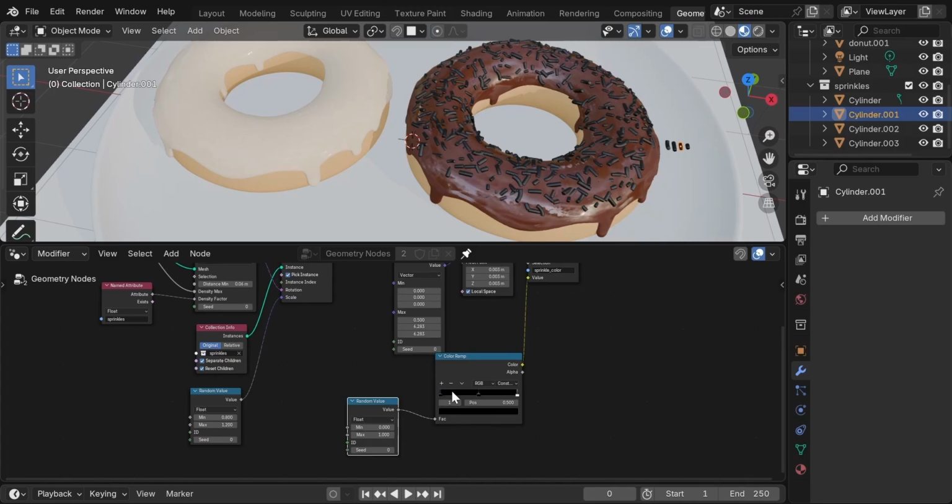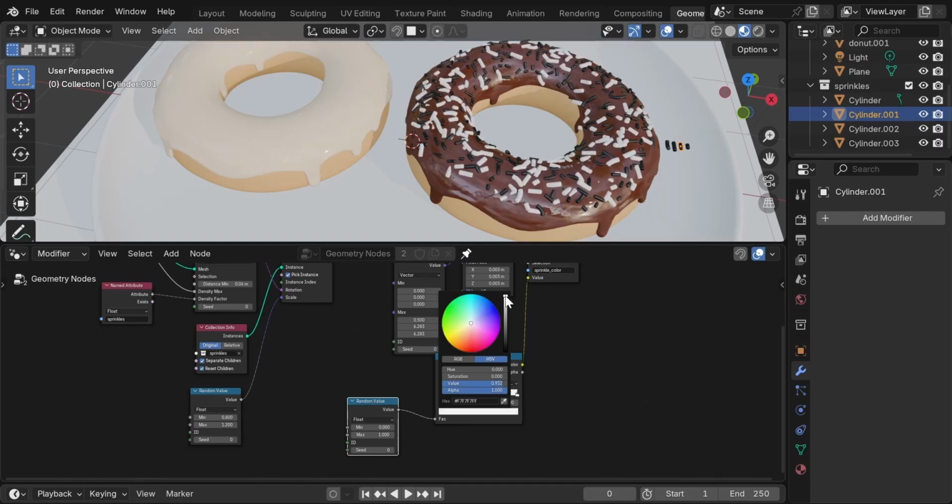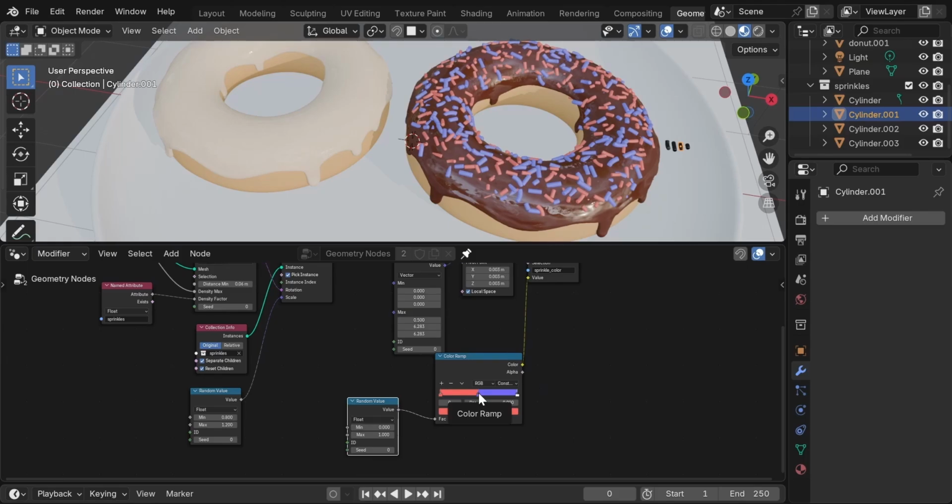Click the plus icon to add a new color stop. Choose a soft light blue. Add another stop, maybe a soft red. Slide the ramp handle slightly and watch the distribution shift. Let's add another color, a soft yellow. Keep saturation controlled. Highly saturated colors tend to feel artificial. For something like sprinkles, aim for saturation around 0.8. Finally, add a white sprinkle.